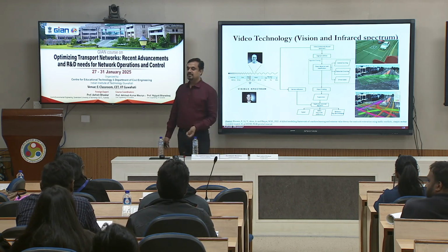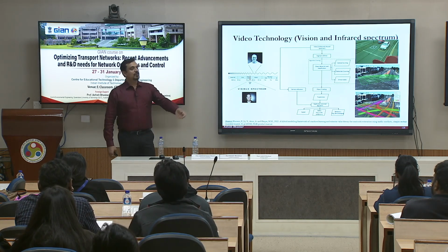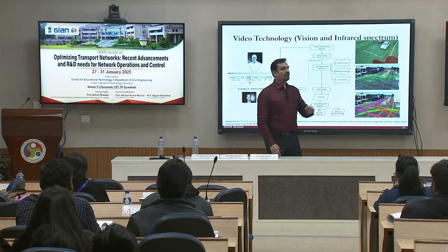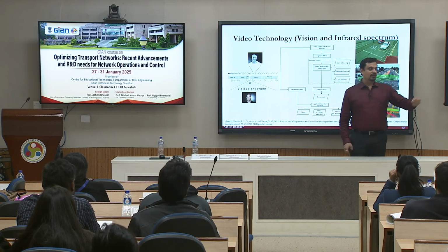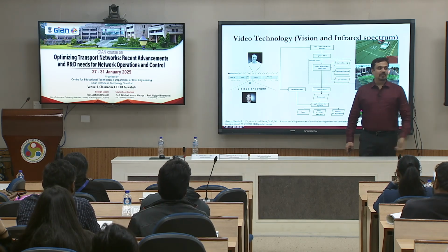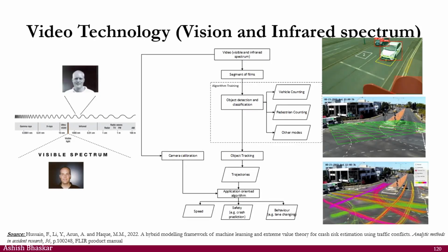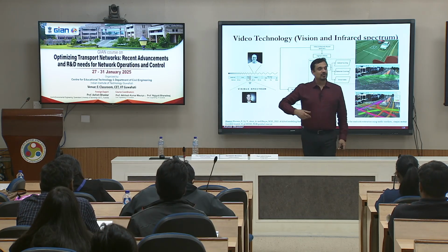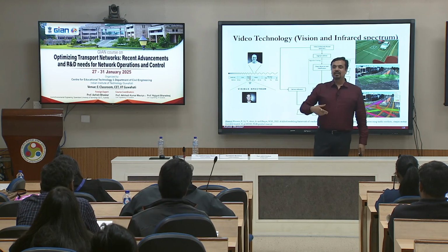The challenge you will face is that buses will be running at a frequency of maybe 10 minutes, 20 minutes, half an hour. Then you only have that much; your data will be having that. If it's a high frequency bus route, then you will have a more frequent data set. With low frequency, you will have data every half an hour or 20 minutes. So that is the challenge you will face. But let's say this is a high frequency route and you are able to get that. Then yes, you can use the bus travel time as a proxy for the car one, but you only get it for one approach. You do not have knowledge of the other ones. So it is valuable, but not giving you the complete picture.